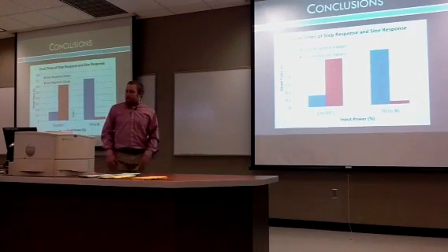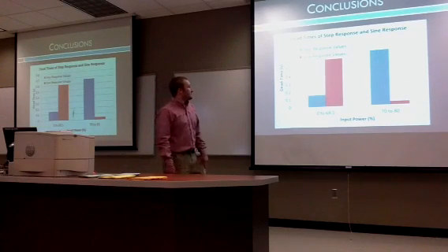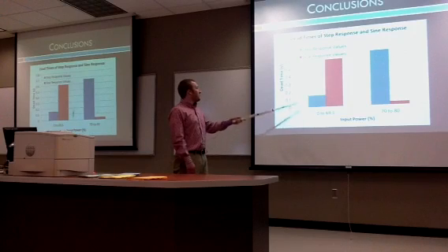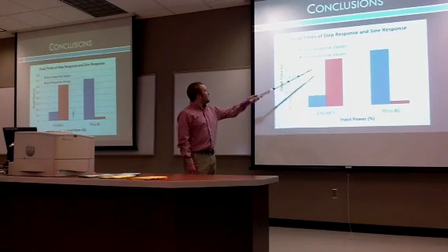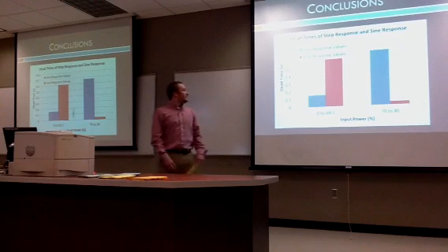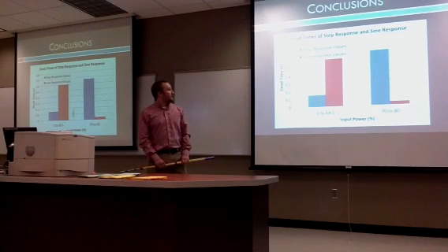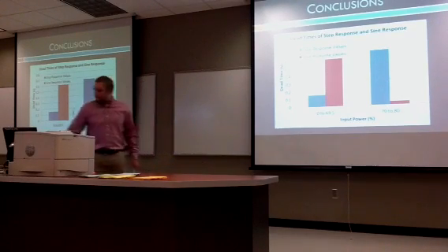Our dead times were dramatically different for 0 to 69.5% and 70 to 80%. We went from about 0.15 seconds for the step response value for the dead time up to about 0.6 seconds for the sine response. And for 70 to 80%, we went from about 0.67 seconds down to about 0.4 seconds.